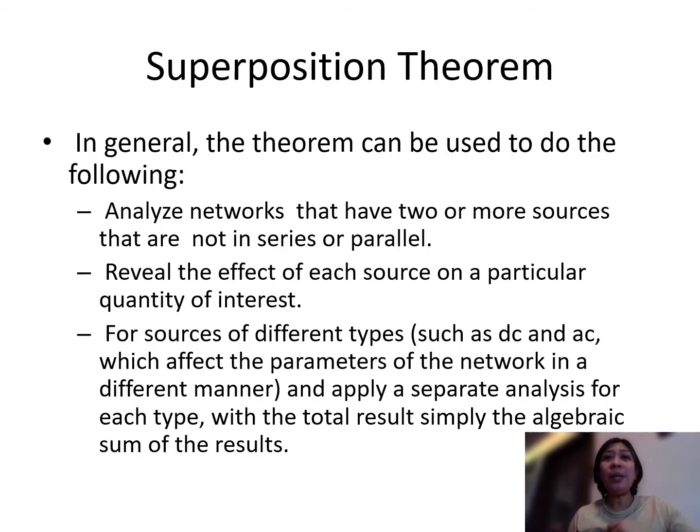So what is the superposition theorem? In general, the theorem can be used to analyze networks that have two or more sources that are not in series or in parallel. This theorem is applicable if we have a circuit having two or more voltage sources or current sources. It reveals the effect of each source on a particular quantity of interest.